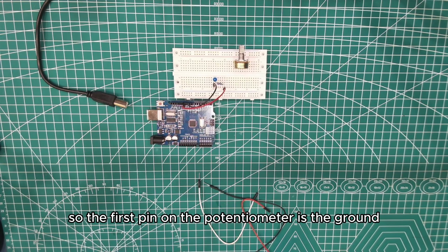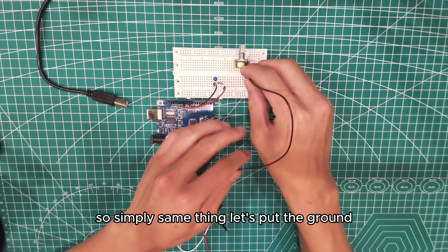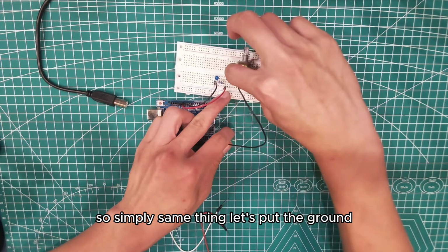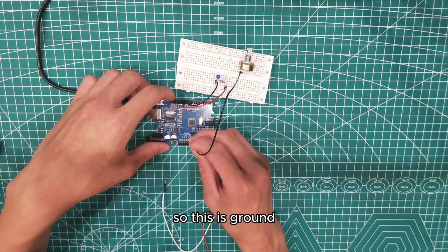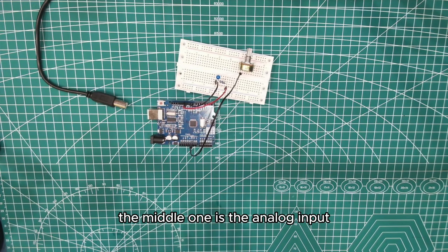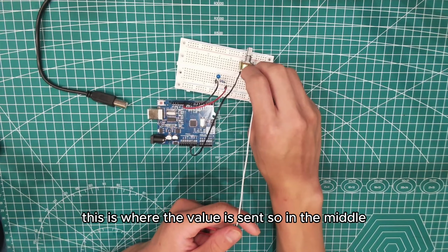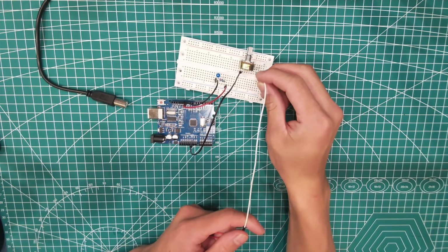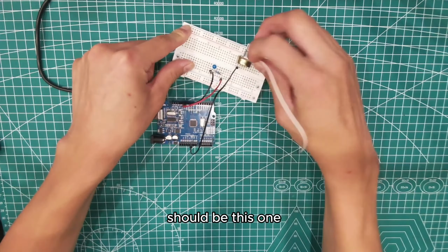So the first pin on the potentiometer is the ground. So same thing as before, let's connect the ground to the ground of the Arduino. So this is ground. The middle one is the analog input. This is where the value is sent. So in the middle should be this one.